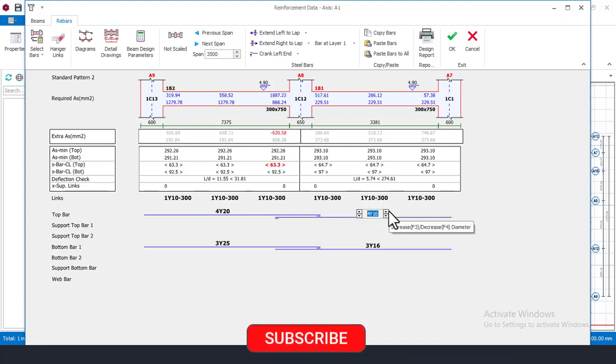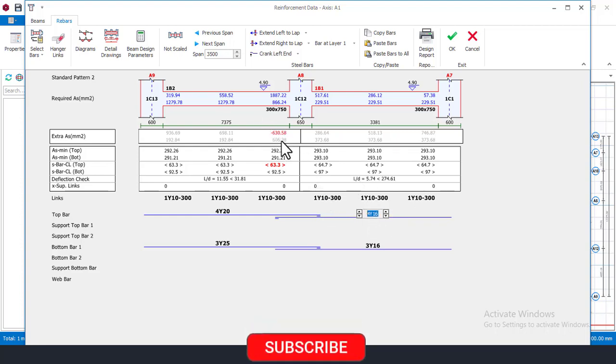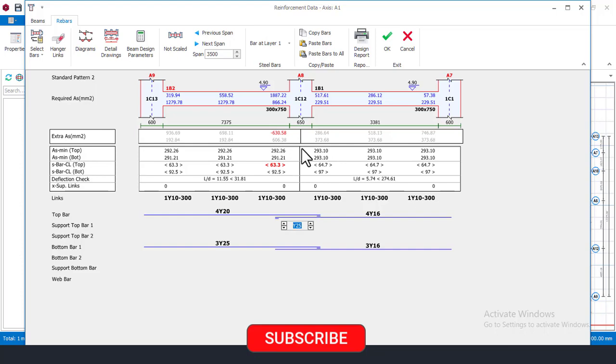And 20 again. Okay, this place is okay as Y16, but here is failing because of the length. This is 7.375 meters and here is 3 point something meters. So that can be used for Y16. And then right now, I'll probably just come here and add my support bar at this place, because this support bar here is failing.